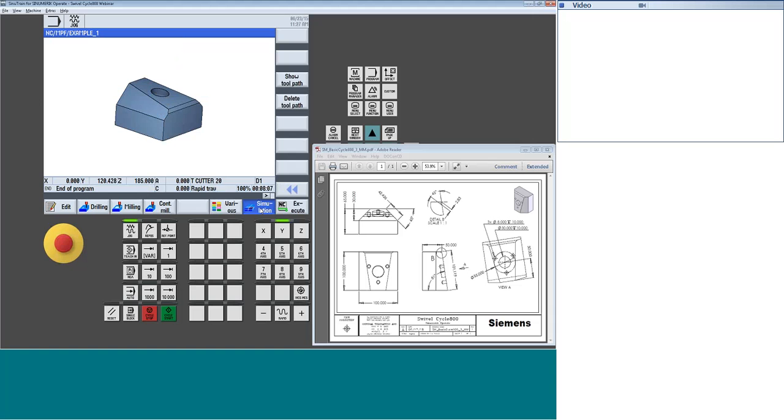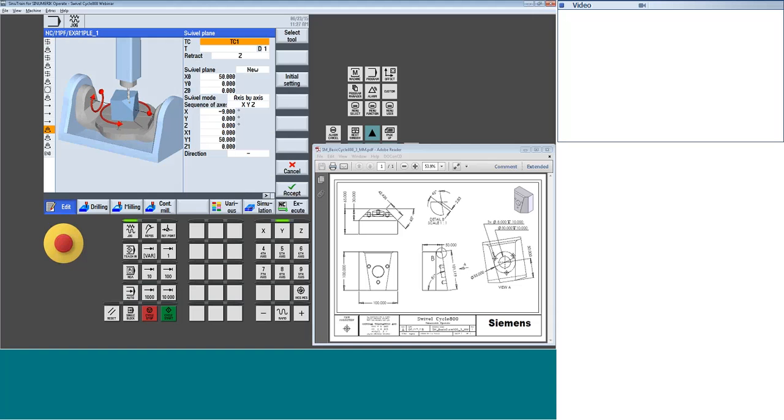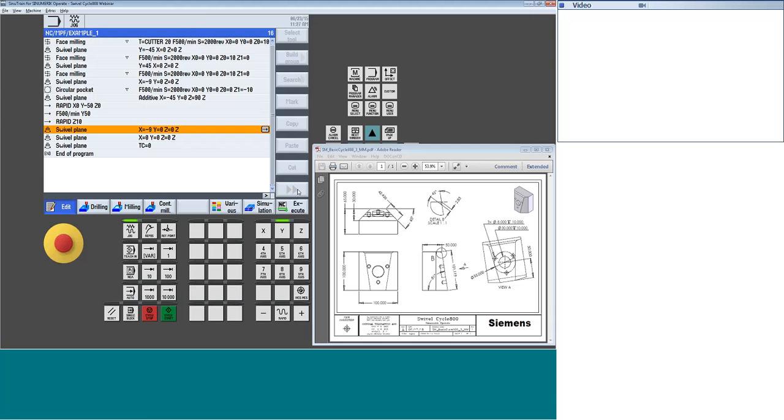So edit it. Once I'm here, now I do want to reinstate my previous swivel, right, because I don't want to keep my 0 where it is. So I'm actually going to use this one, and we'll bring it right down there. So that is putting my 0 back to the center of my pocket feature, and I'm sitting at a 9-degree rotation. We're going to go drill some holes, do some basic drilling.